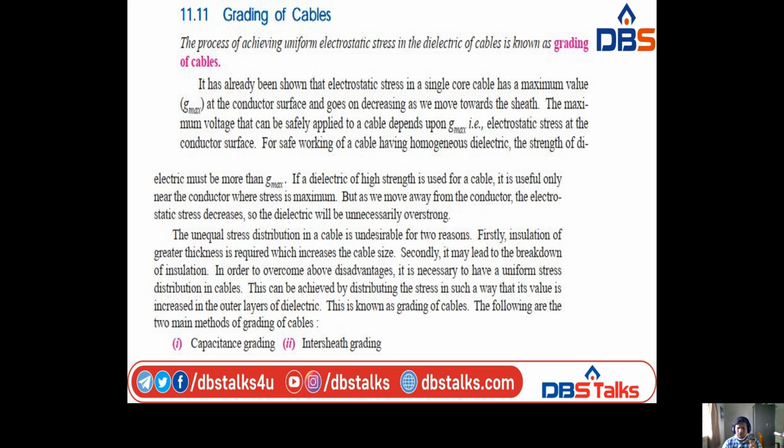Why? What is the necessity of grading of cable? Because of unequal stresses, insulation size increases and the insulation breakdown may occur. To overcome these two, grading of cable is necessary. Here two grading methods are there, capacitance grading and Inter-Sheath grading.